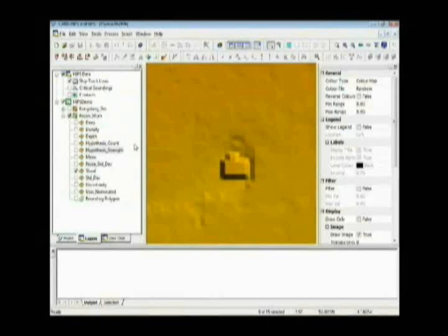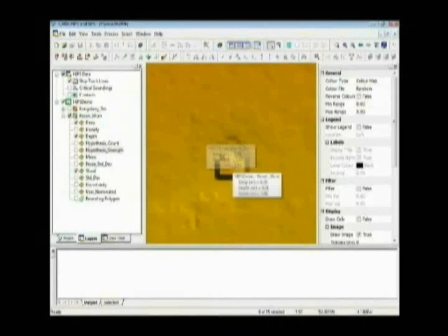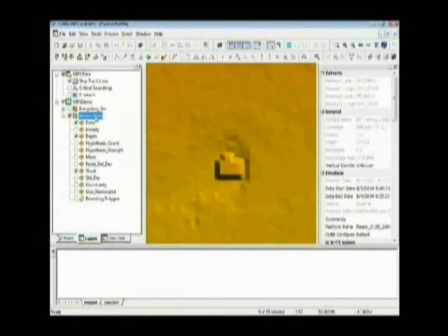Another feature that I really like here is we've got the ability to turn on all of the layers at once. So I'll turn on the deep and the depth layer, and while only one displays, you'll see that with my tooltip, it's actually showing all three layers at once. I've got the value of my depth layer of 8.2 meters, which is my current depth estimate or hypothesis. I've got the deepest sounding for the node, which is 8.26, and I've also got the shoaler sounding for the node, which is 7.46.